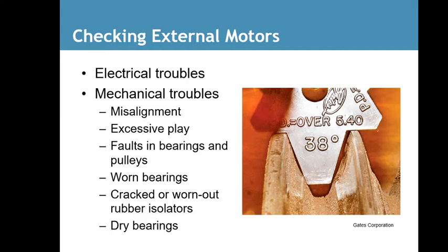They do make these in other shapes, so you can check if your pulley is worn out. You can see in this picture mainly the right-hand side of that pulley has really worn out, so that means the belt's not going to stay on very long. It could pop off or it could wear the belt out prematurely. So this pulley would need to be replaced.